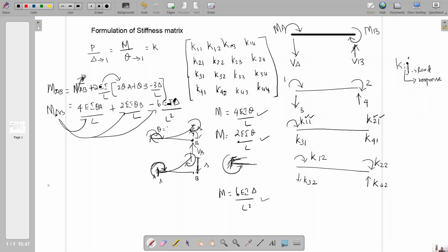shear force, because if you consider the same moment direction, I am applying like this, because you may come across this case in moment distribution method by calculating the horizontal reaction. I am assuming HA is in this direction and HB is in this direction, and if you consider moment at A, moment at B, you can take moment at B to calculate HA.